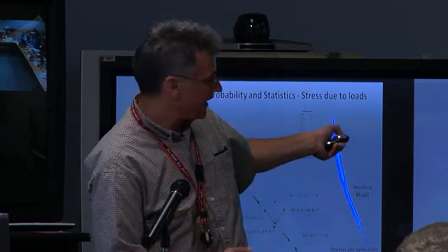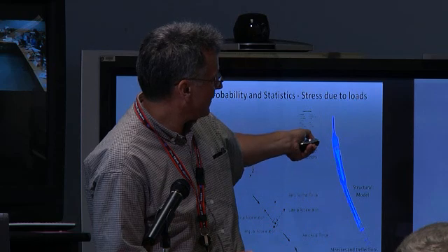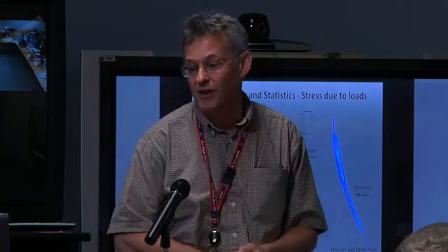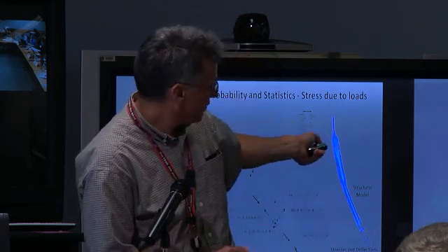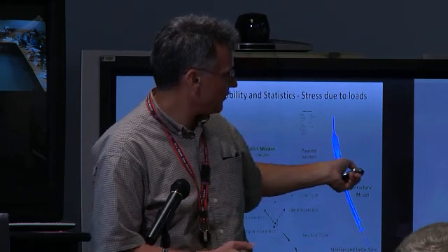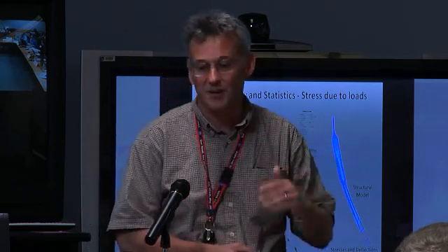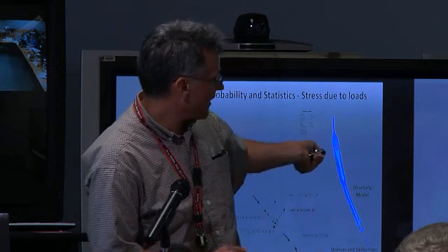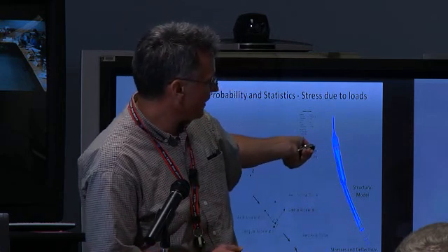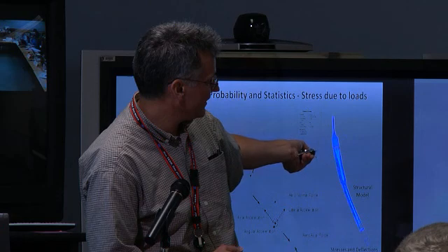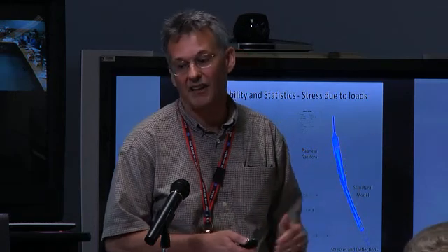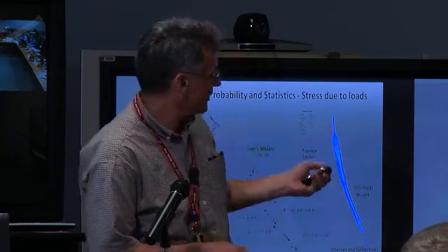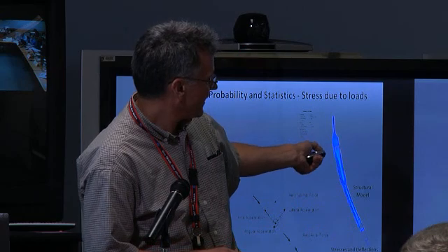Run that through there, and what happens is they find, like the footprint that Juan showed for landing, this is a footprint here of angle of attack going through a control system. So you essentially want all your extreme loads to be inside that ellipse there, which is again like a 99 percentile. At 99 percentile, all your loads are inside that area.